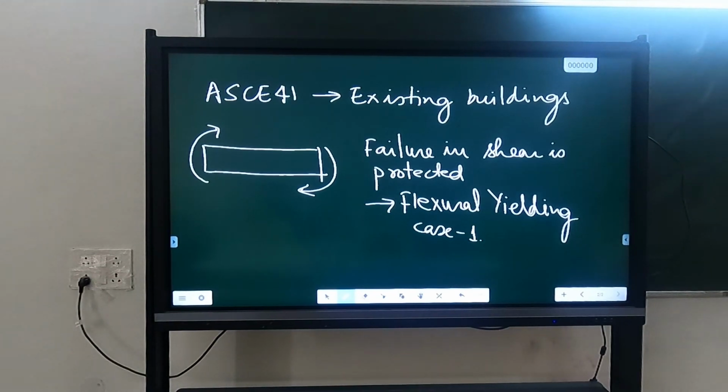Flexure. When the failure is occurring in flexure, we will get the maximum ductility. And when the shear failure is governing, we will be brittle, we will have very little ductility. And in case of flexure shear failure, we will have some variability. So that's why those three conditions are there. You can check that the value of A, B, C are changing depending on whether it is flexure failure or shear failure or flexure shear failure.